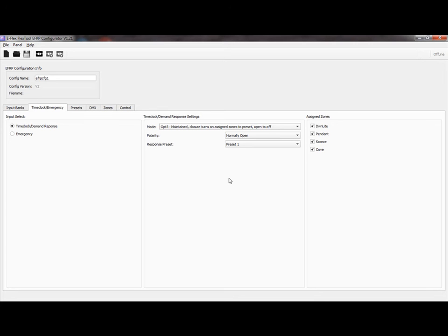This means with all lighting levels at 100%, the maximum lighting power must be reduced by a minimum of 15%. That is, demand response will enforce a maximum level. The maximum level is set using a load shed value. The demand response level is 100% minus the load shed value.